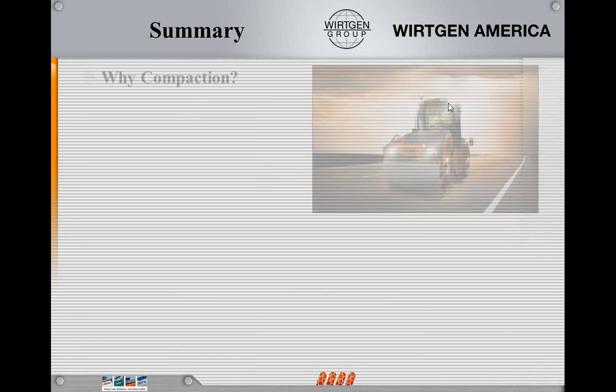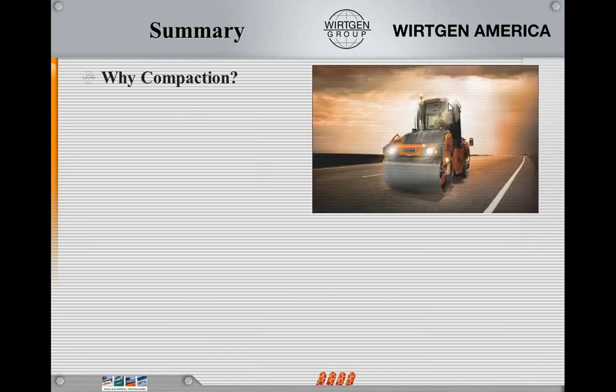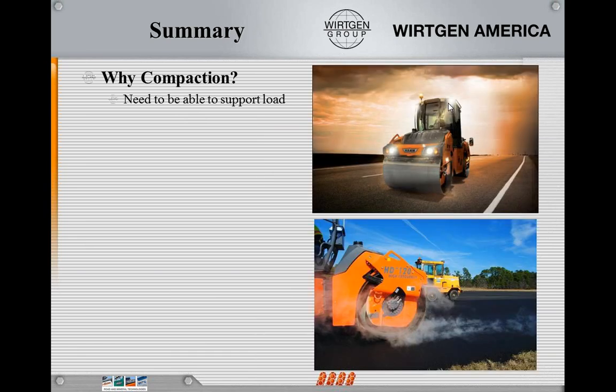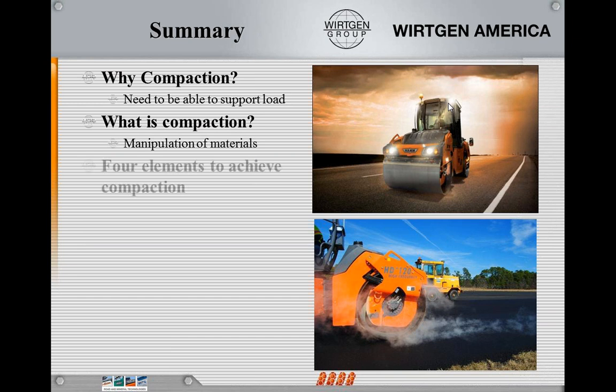So in summary, why compaction? We need the ability to support a load. If we can't support a load, we are not going to be able to have that road stay together and have longer lasting roads. What is compaction? It's basically just a manipulation of the materials. On the soil side, when we manipulate them, we need to add proper moisture content. On the asphalt side, the liquid is our lubricant, so we need to make sure we have the proper amount of that as well.